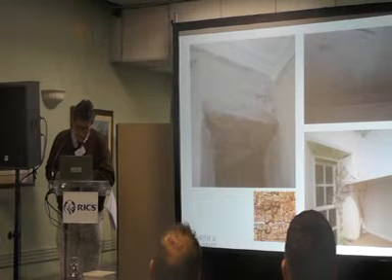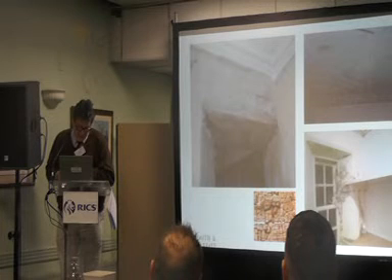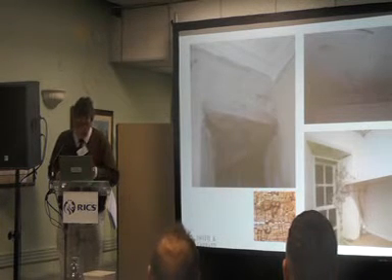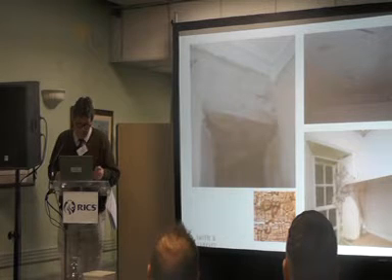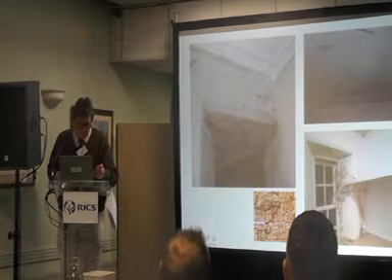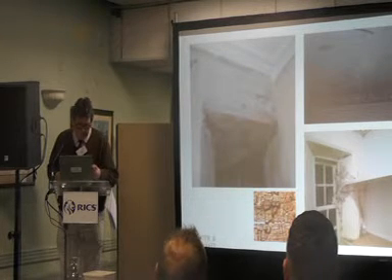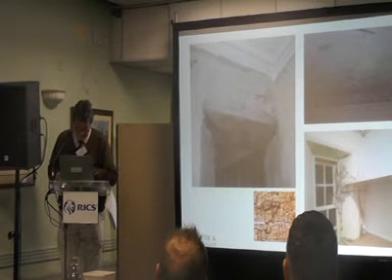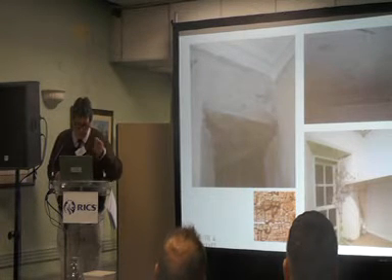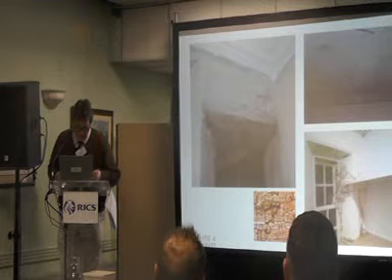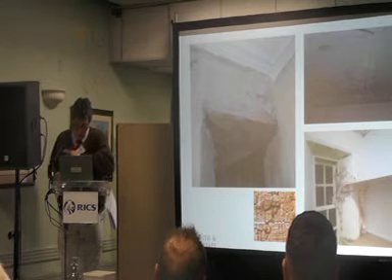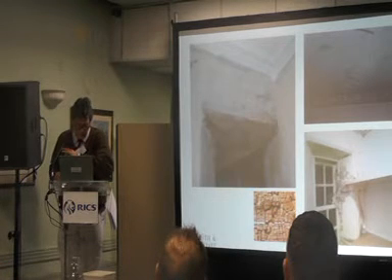My assistant had been to see it the week before, and as I approached this room, he said, "Oh yes, this is the room with the dry rot." I opened the door, and it didn't hit me. No smell. So I looked very carefully at the dry rot fruiting body. I gave it a wee prod, and it broke off like a biscuit. I'd been in the floor above, and I knew there was a bathroom in the floor above, and I knew it served, should we say, a late teen boy's bedroom.